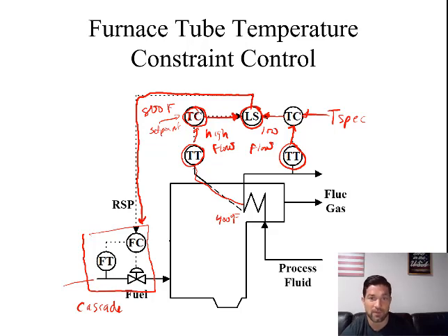Under those conditions, when this is operating under safety constraints, the process constraint is trying to get us to our maximum set point, which is 800. And so this is going to be a high flow. Therefore, relative to normal operation, when this is operating safely, this is a high flow relative to this, so we need a low select.